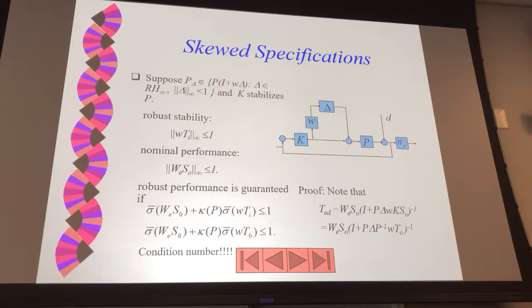So if the minimum singular value is 0, then this matrix is singular. In other words, if a matrix is singular, then its condition number is infinite. I can also check sigma bar divided by sigma under bar, this condition number. The bigger it is, the closer the matrix is to singular. Make sense? It is also true for systems. If your maximum and minimum singular values have a very big distance, then your condition is not considered as good.